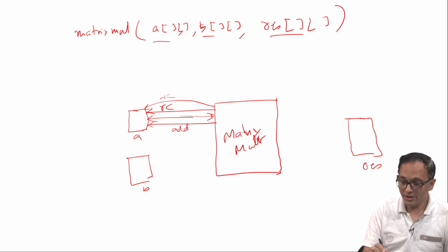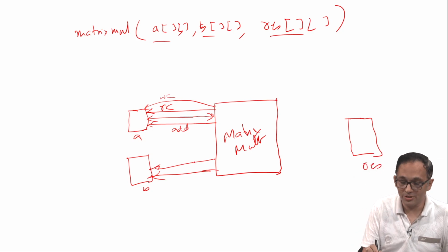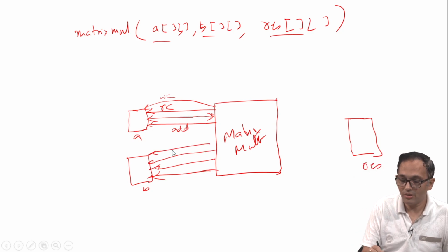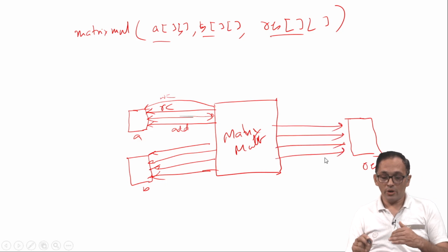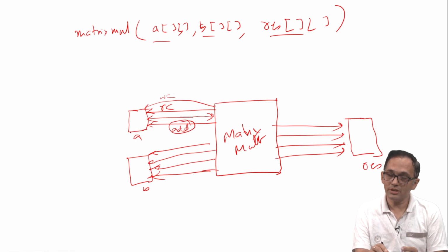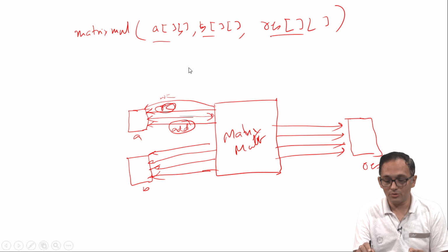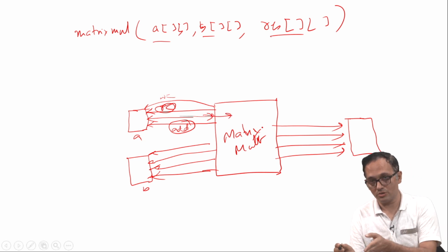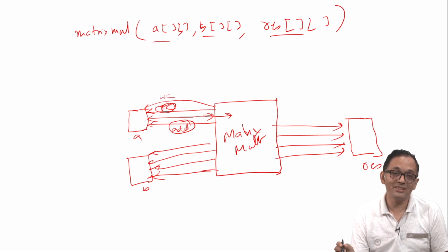So, these are the signals you need, right. For each such memory, it will effectively create this many. There will be one address, maybe a read address, and the write address can be different also, there will be data, write enable, read enable, all those things will be created for each of these memories. And whenever you want to read the data, it will give the address of the value you want to read, with the corresponding read enable equal to 1, so that the corresponding value will come through this data port into the module, right. So, this is how the interface is going to be created, and that is exactly being done.